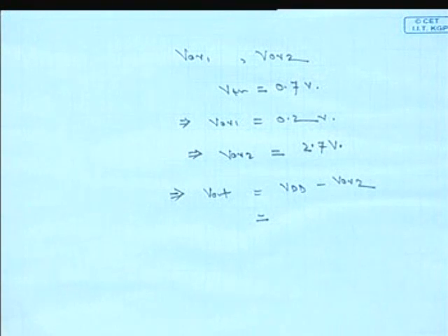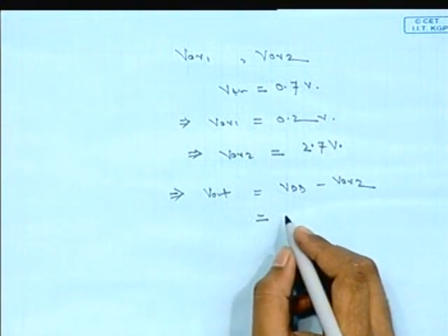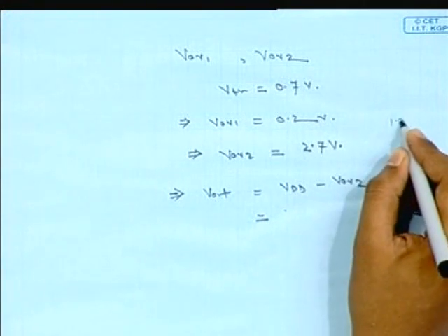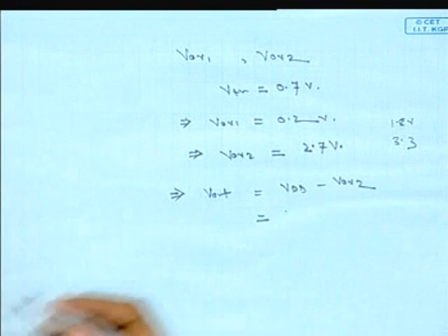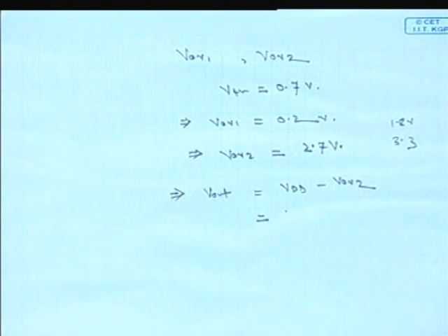If we take CMOS technology, you readily know the supply voltage. In that case VDD may be 1.8 volt, it may be 3.3 volt or so, and see the effect of that particular VOV2. If we take VDD equal to 3.3 volt, and VOV2 is 2.2 volt, then we are getting a maximum voltage swing of only 0.6 volt. So there is a great trade-off between the output voltage swing and the gain, and the input dependency is on the gm and the gain of that particular amplifier.